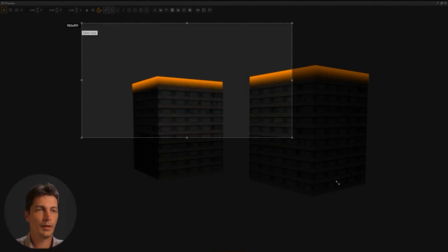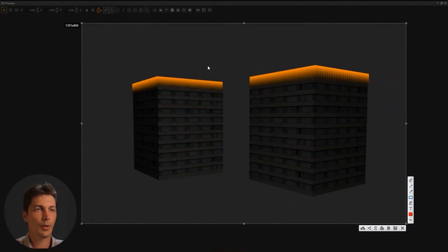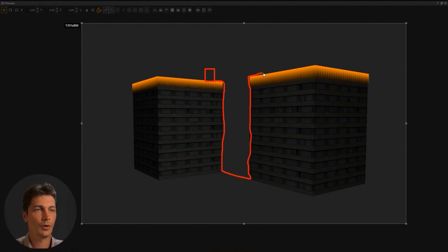This can be implemented in two ways. The first option is when the Lightmaster player head unit is positioned, for instance, on one of the buildings, and we transmit ArtNet to the second building via a cable connection that links the two locations together. If there is no possibility to lay a cable, then we have another synchronization method: by time, assuming the presence of the internet. This is how computers and smartphones synchronize time, and this is the method we will talk about in this video.